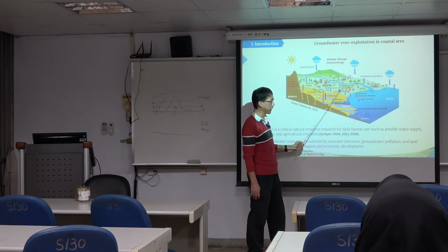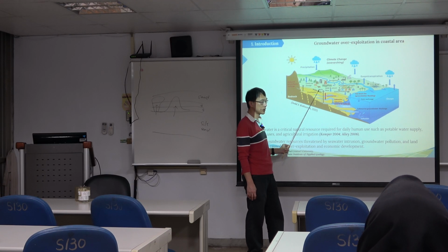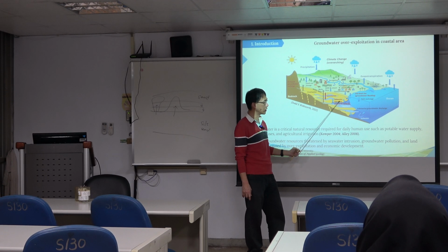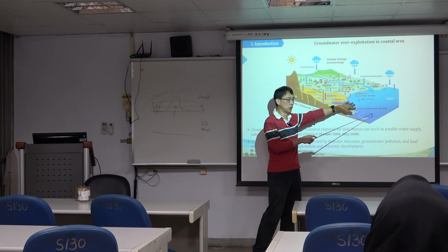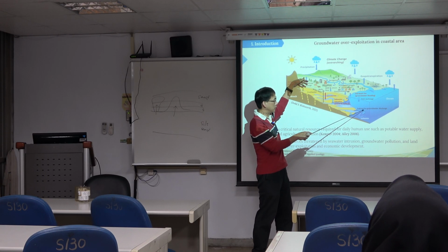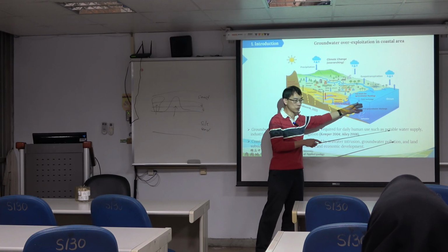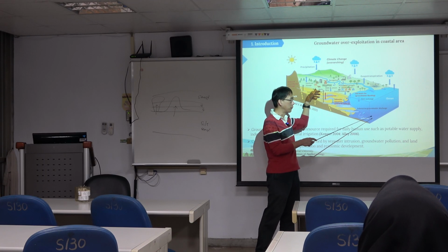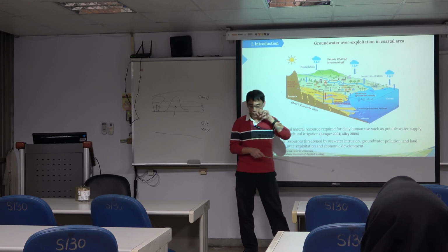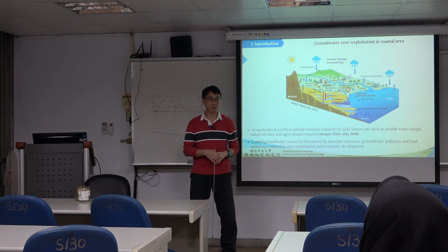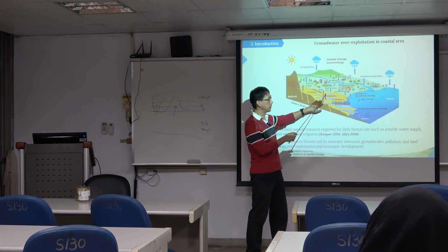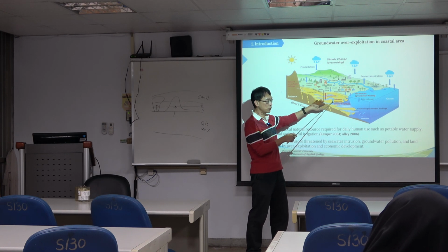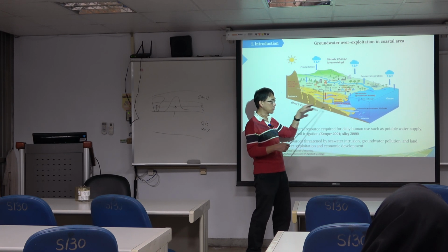Okay. So in the coastal area, we know the seawater and groundwater exchange or interactions are quite complex. So there might be seawater intrusion problems. We might have submarine groundwater discharge because naturally this elevation is high and this elevation is lower, so the groundwater flows from the land to the ocean. So we commonly have gradual outflow patterns. We call that submarine groundwater discharge. And another, if you pump too much water inland, you might induce seawater intrusion. Okay, so they become like interactions.